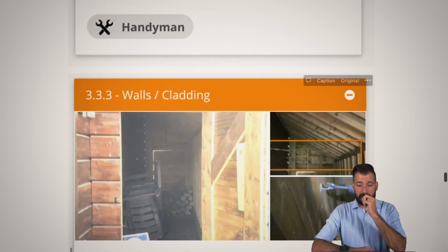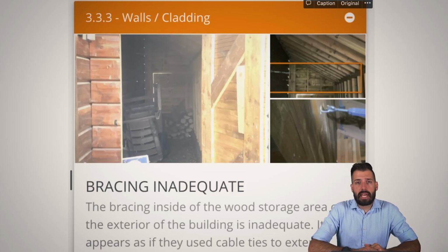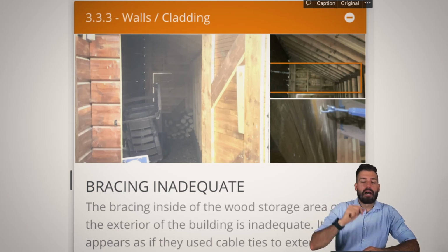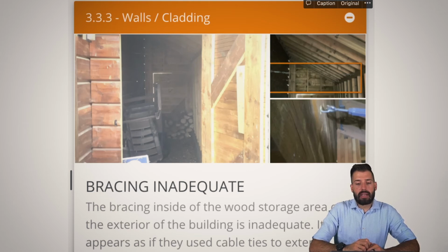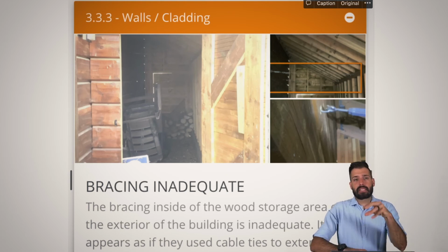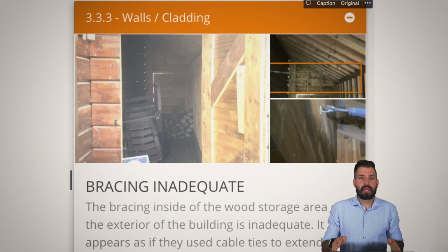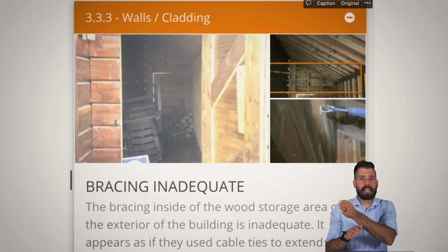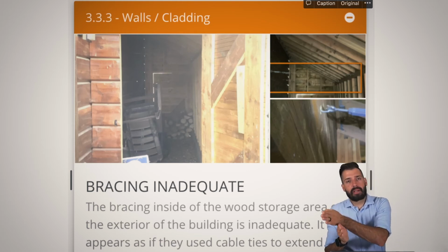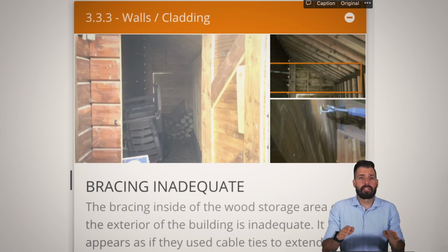So this was interesting. This was an afterthought, and this is a wood storage shed that is physically attached to the house. And what happened was they built this wall, and so the wall that we have right up over here was basically built, and at the very top picture, they filled it up with wood. If you were to take sand and just let sand go, the sand is going to make a natural pile just like this. And the same thing happens with wood. Wood is going to make a natural pile just like this. And what that means is that any wood that I stack outside of this pile is actually pushing up against that wall or wanting to fall off the pile to get into this perfect little triangle here.